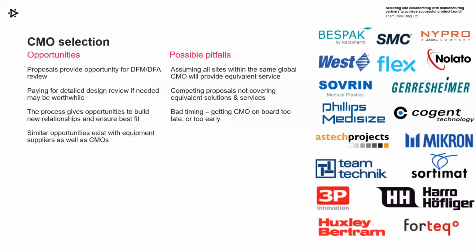So thinking about opportunities, getting CMOs involved and getting proposals gives an opportunity for some DFM, DFA input. If you haven't got that, then it is worth thinking about getting a design review by a CMO or manufacturing experts who may not be the final manufacturer of your product, but who will be able to give you expert input. We've certainly done that in the past, gone to speak to auto assembly equipment manufacturers or tool makers, even if they're not going to be providers of the final solutions. They're often willing to help on a consultancy basis and provide very good input that's very worthwhile.